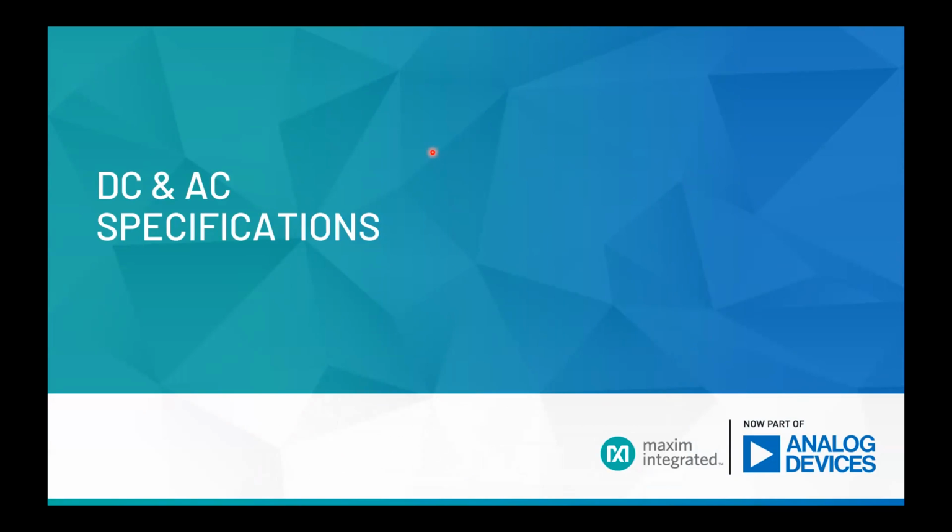DC specifications are broadly time domain heavy, right? Things like offset, how is the fidelity of the signal, the monotonicity, right? How much is the signal changing? All these factors are DC. And AC specifications are more like whatever you see in a Fourier transform, right? Things like what is the harmonic distortion, harmonics, then my spurious free dynamic range. All these things are AC specifications.